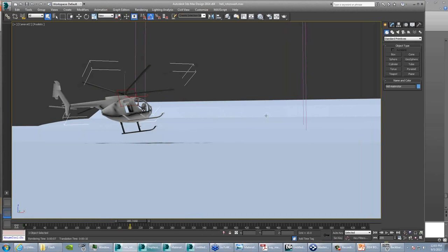Okay, the next question: are you aware that the camera correction modifier does not work with the caustic solver? How do you get around that? Yeah. Am I aware that the camera correction modifier does not work with caustics, and how do you get around that? I am aware of that. I know NVIDIA is aware of that, and I do not know of a way to get around that other than just turning off caustics.